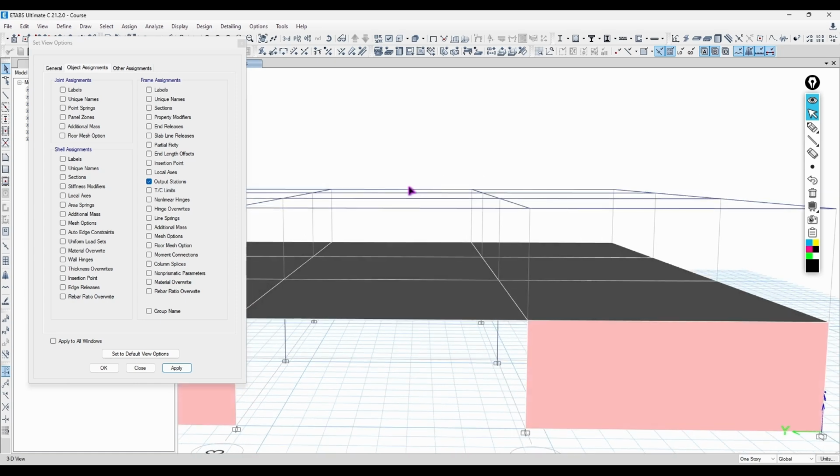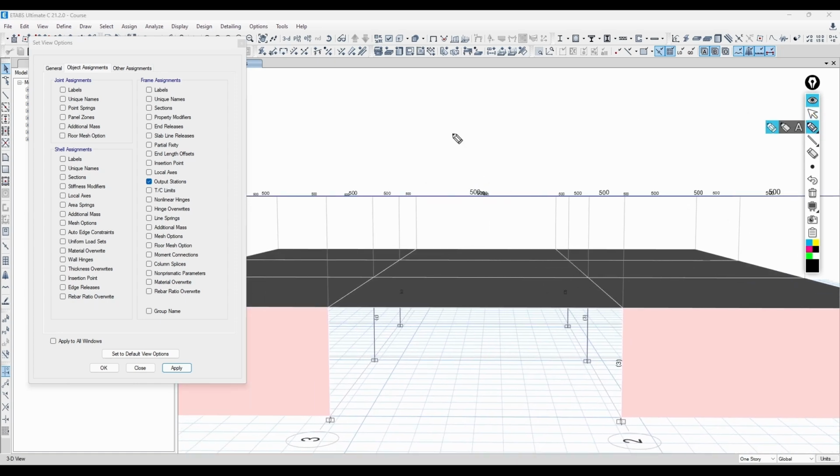Why? Because usually, let's just try to straighten this out. When you draw a bending moment on a beam, you don't do that. It's not like a straight line, right? It's more of a parabola, something like this. So you need a lot of points to give you this kind of parabola feeling. That's why it has 500 stations. So let's say this beam is 5 meters, right? It's going to divide it into 500 pieces.